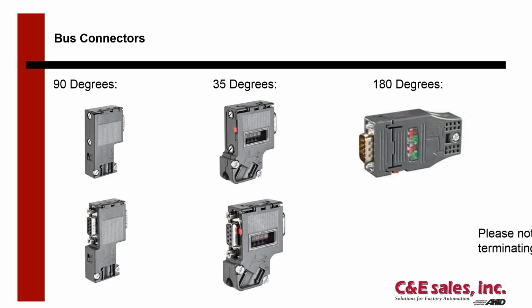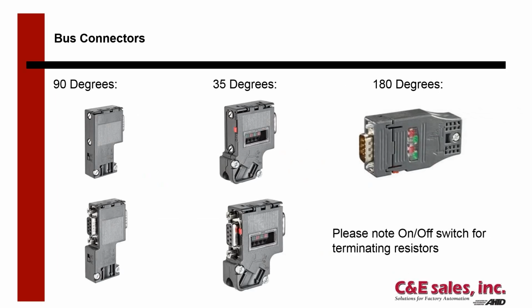But before that, I want to point out something. If you notice, there's an on-off switch on the back of all of these connectors. You can see it here on the 180 connector. It's down on the bottom there. You can just see it in red. That's for a terminating resistor. We'll talk about when that terminating resistor needs to be on and when it needs to be off, but it's very important, so I want to highlight and show you what that switch does. It's for a terminating resistor.